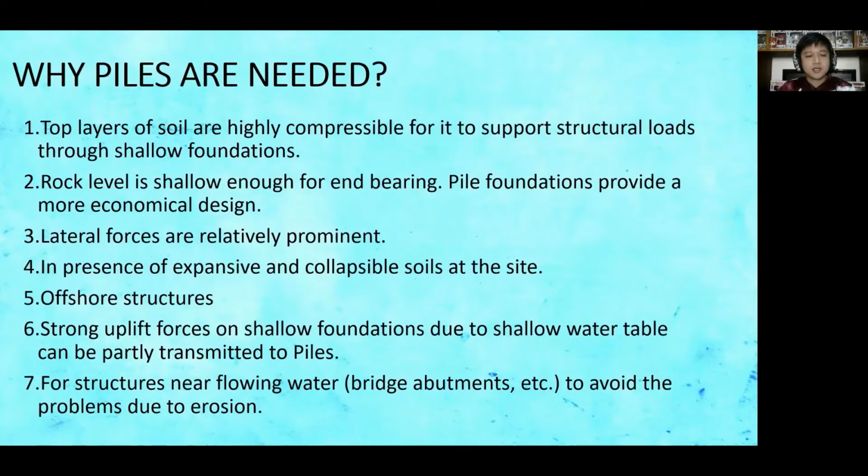Fourth, in the presence of expansive and collapsible soils at the site. Expansive soils are clayey soils, and collapsible soils are soils with a very large volume of voids, such as honeycomb-structured soil. Fifth, offshore structures, such as bridge piers and structures built on or near bodies of water.